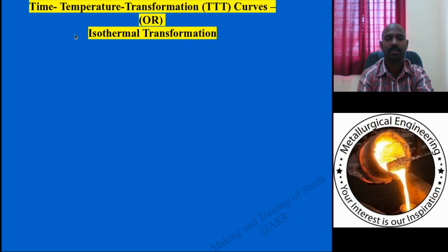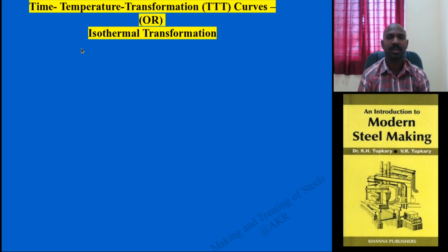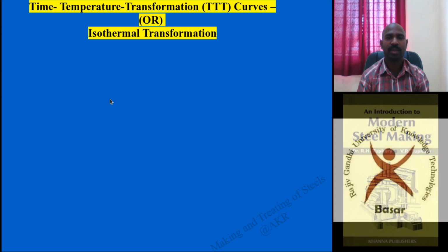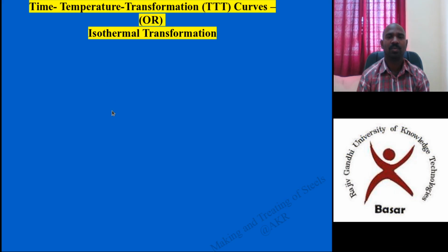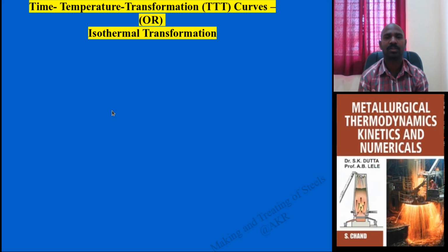A constant temperature is followed and steel transforms from the austenite parent phase. Mainly eutectoid steels are taken and studied under this section, and various carbon compositions of steel can be studied with respect to the eutectoid steel, along with their transformations, applications and suitable properties.